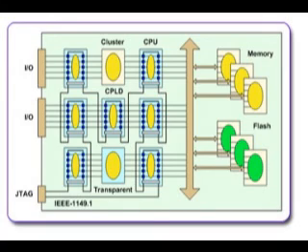Boundary scan, as defined by the IEEE STD 1149.1 standard, is an integrated method for testing interconnects on printed circuit boards (PCBs) that are implemented at the integrated circuit IC level. The inability to test highly complex and dense printed circuit boards using traditional in-circuit testers and bed-of-nail fixtures was already evident in the mid-80s. Due to physical space constraints and loss of physical access to fine-pitched components and BGA devices, fixture cost increased dramatically while fixture reliability decreased at the same time.